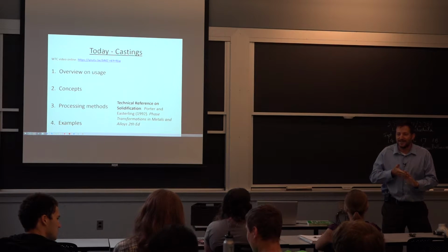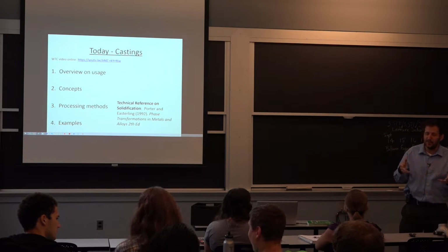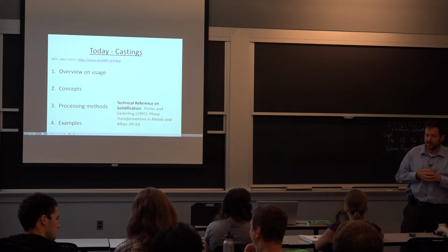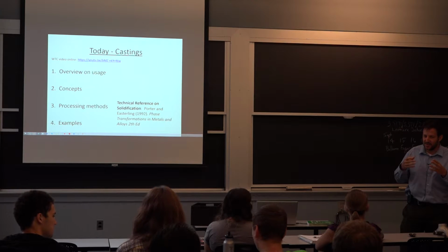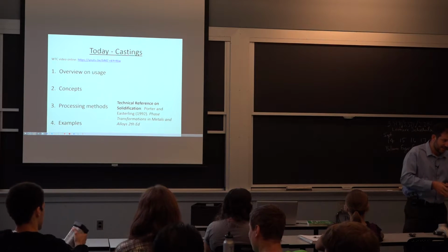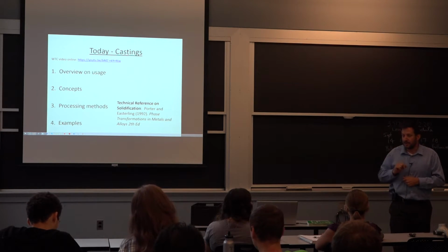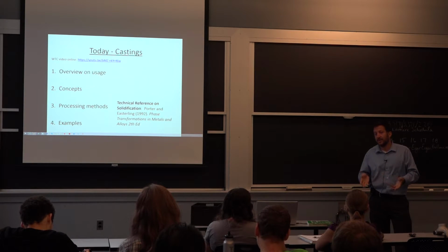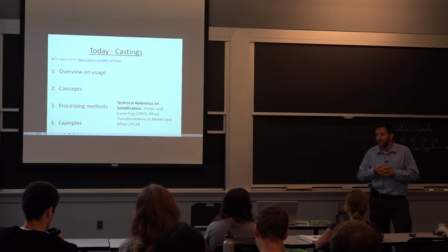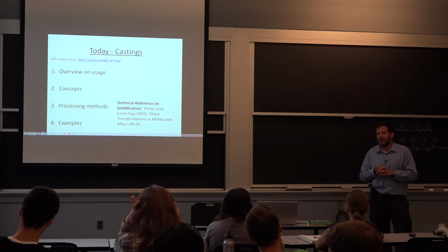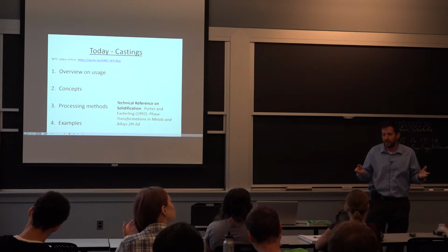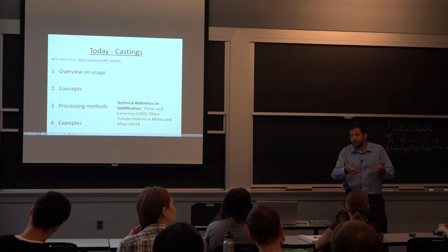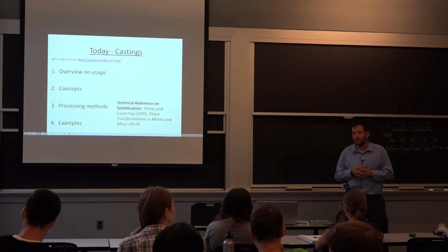But the emphasis is, hopefully, one of my objectives for this semester, for you to realize that some stuff makes sense to be cast, some doesn't. In this particular case, if you try to cast the steel, it's very high temperature. By itself, it can be done, but it's a difficult process. And if you need to change any of the dimensions, now you have to make a new mold and requalify all your processes.